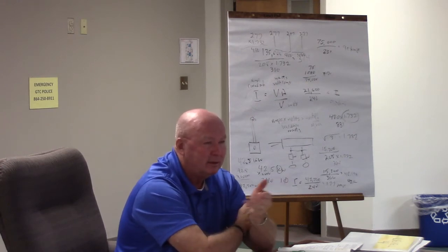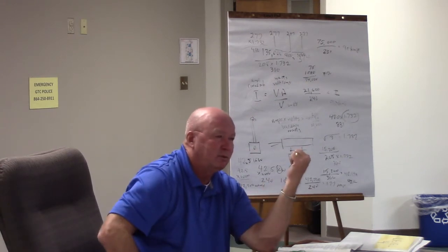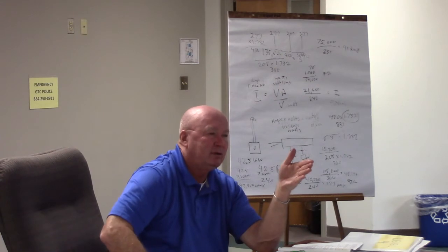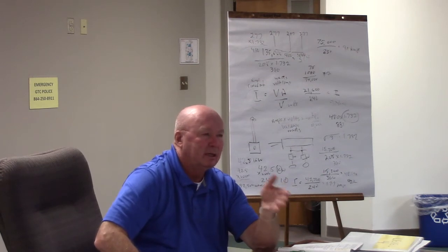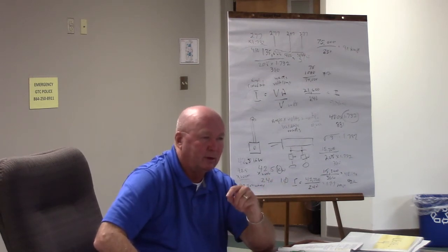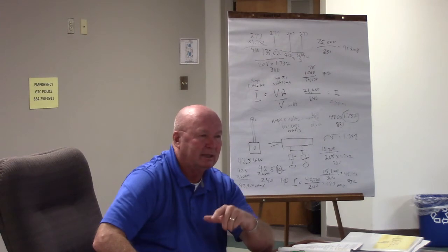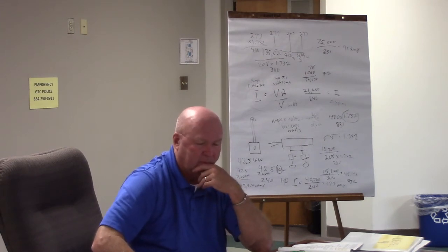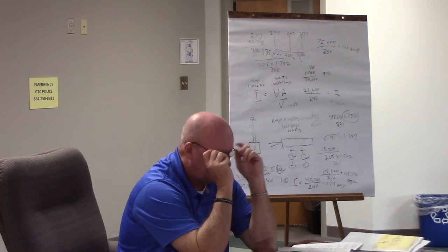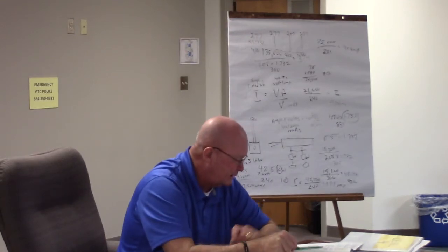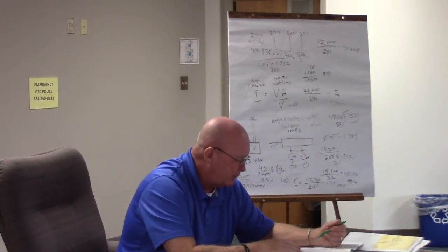If not, then you have to go back to 110.14(C), and you have to use either under 100 amps, which puts us in the 60-degree column, or over 100 amps, or number 1 or larger wire, which puts us in the 75-degree column. I'm just thinking through why they might have used number 1, but I can't come up with a solution. All right. Let's look at example number 4, and then we'll take a break.